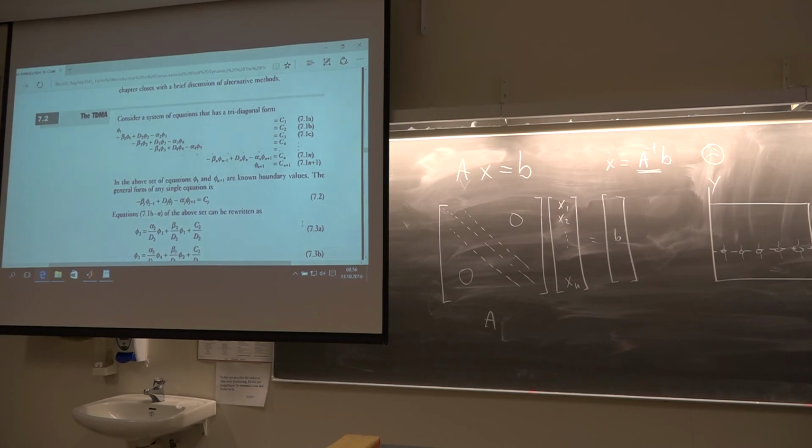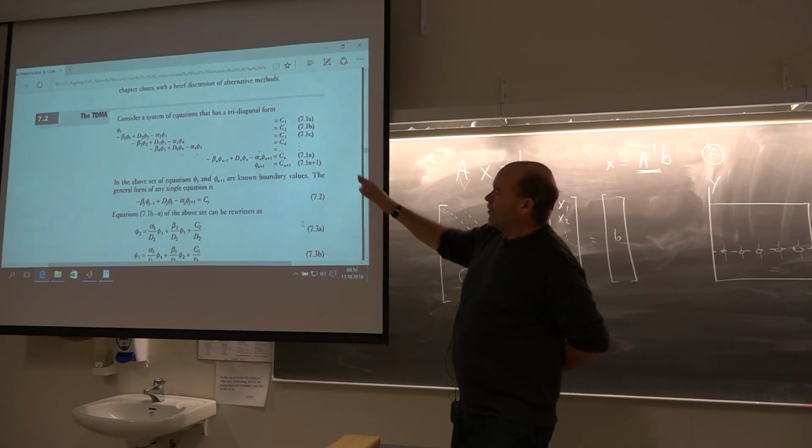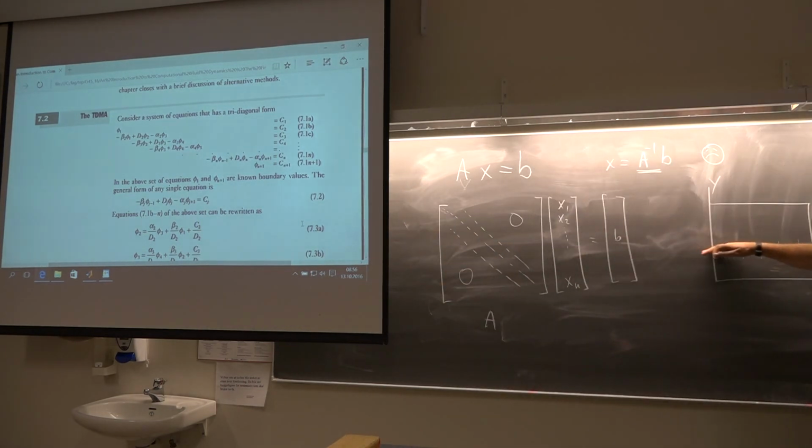So a line solver will actually use this Thomas algorithm for one single line throughout your domain, and just solve it. It's very easy to solve, it doesn't take much CPU. It's a direct method for this line alone. Of course, it's not correct because now you're treating the neighbors as constant.